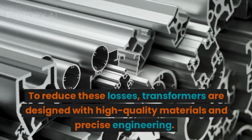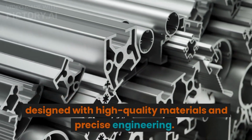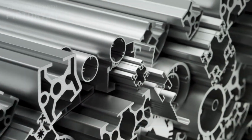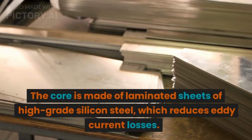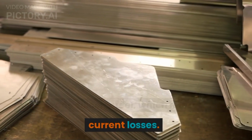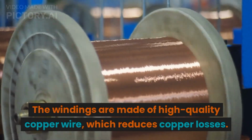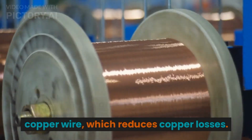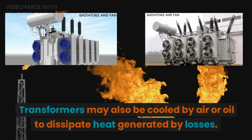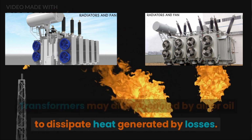To reduce these losses, transformers are designed with high-quality materials and precise engineering. The core is made of laminated sheets of high-grade silicon steel, which reduces eddy current losses. The windings are made of high-quality copper wire, which reduces copper losses. Transformers may also be cooled by air or oil to dissipate heat generated by losses.